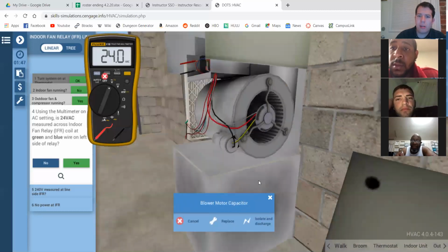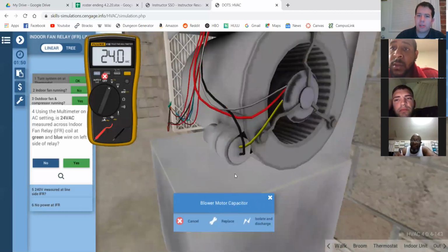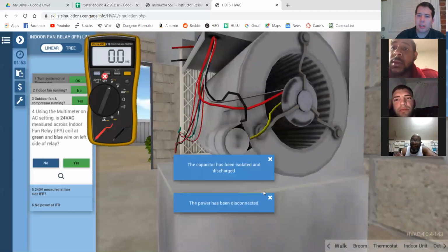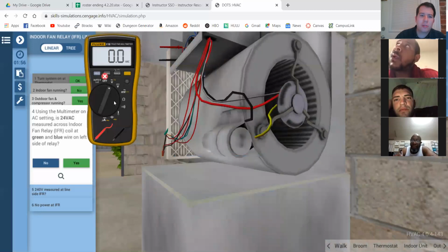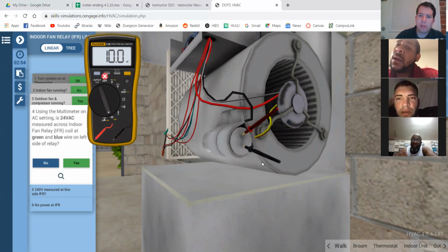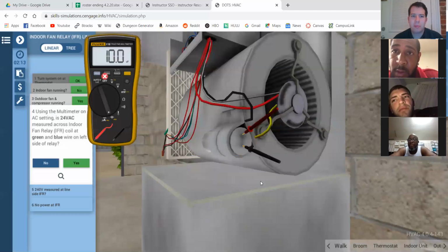So how do I test a capacitor first of all? What have I got to do to test a capacitor? The meter, right? Yep, you're going to use your meter. What setting am I going to have on the meter? What am I going to look for? Is it amps? Nope. It's not ohms, right? On y'all's meter, it is on the ohm setting. If you go to resistance and you hit select 3 times, it's going to bring up a different thing that's called microfarads.